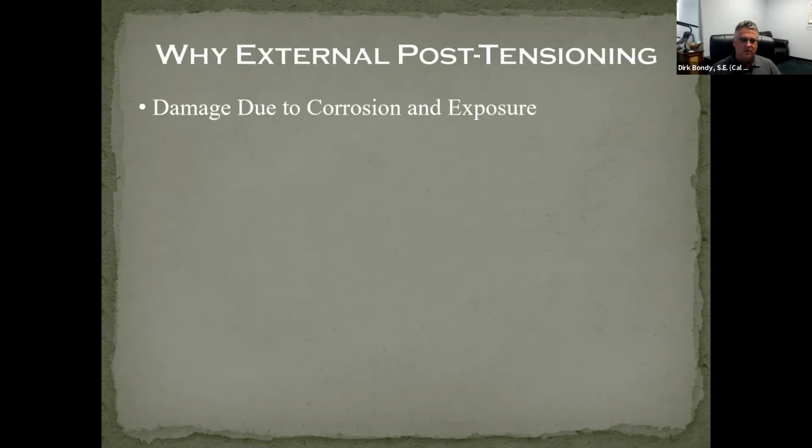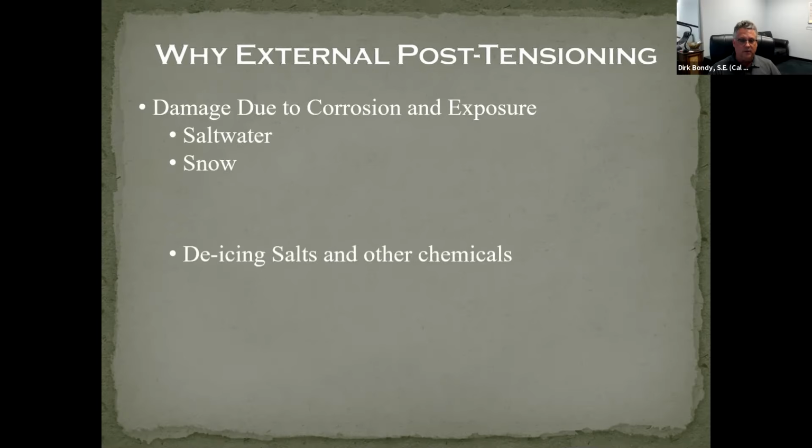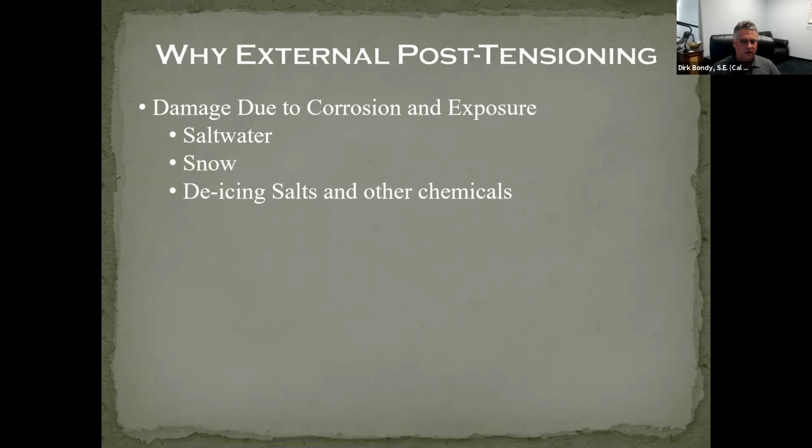Well, when do you consider external post-tensioning? When you have damage due to corrosion and exposure to salt water, snow, de-icing salts, other chemicals, being close to the ocean or being up in the mountains has been where corrosion accelerates. And it's largely due to somehow getting salt, water, and air mixed with metal.